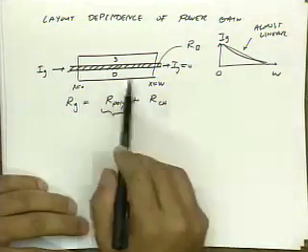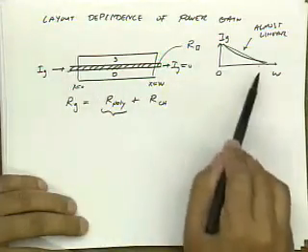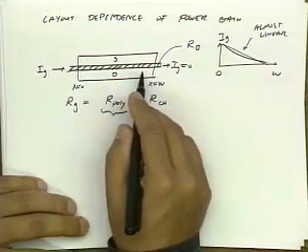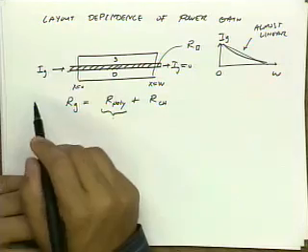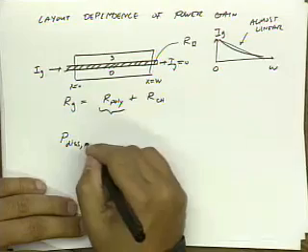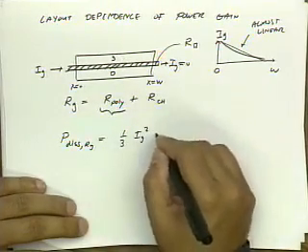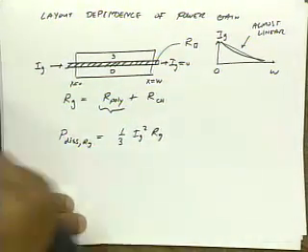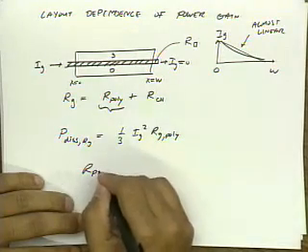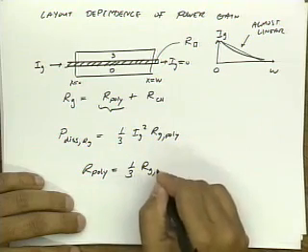Now if you calculate the power loss to this piece of wire, this polysilicon, if you put in a linear current like this, you'll verify that the power loss goes like 1/3 of Ig squared times R. So the power dissipated in Rg is 1/3 I gate squared Rg. In other words, R poly is 1/3 R gate poly.